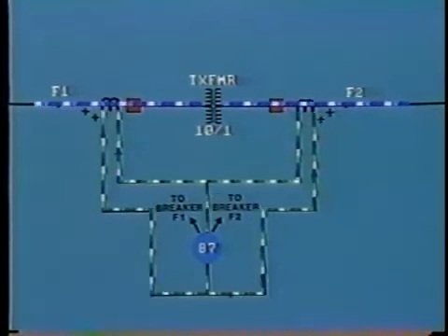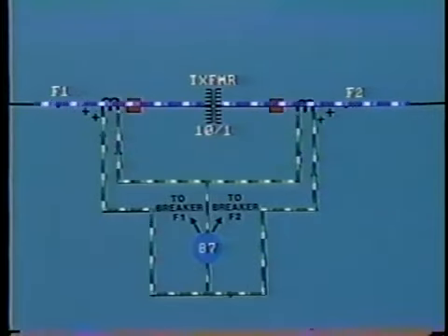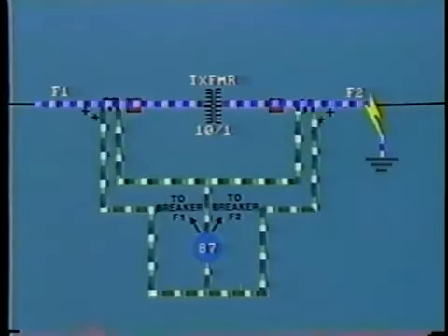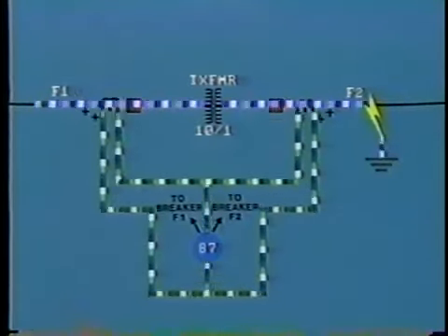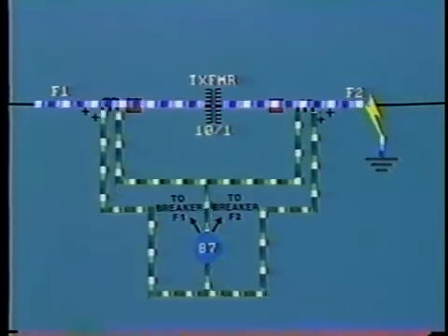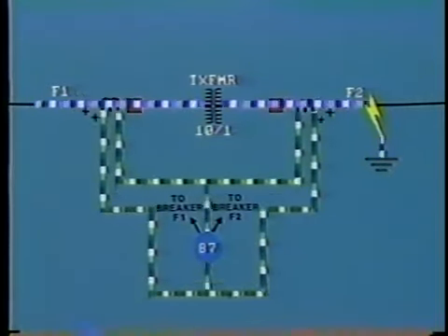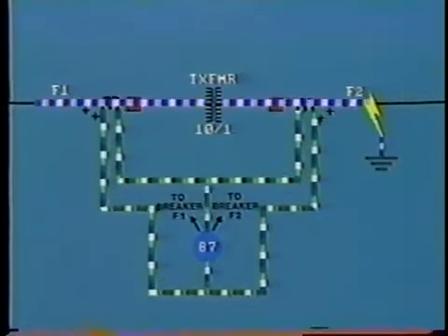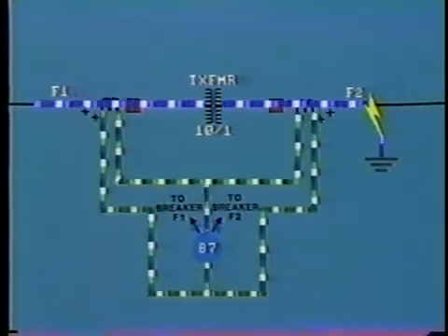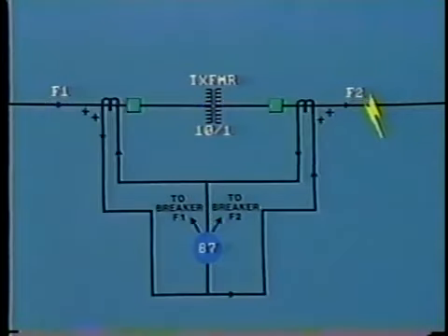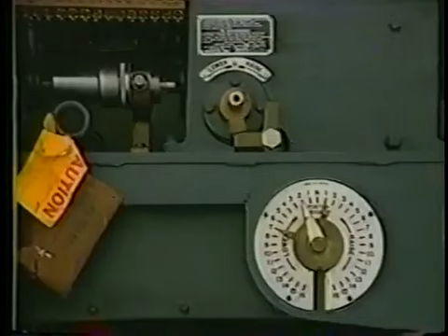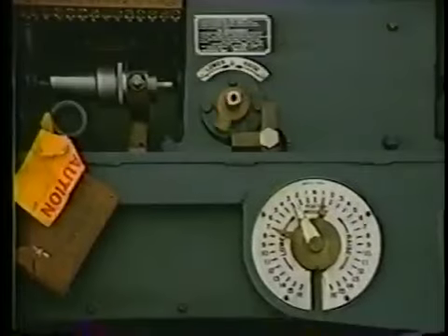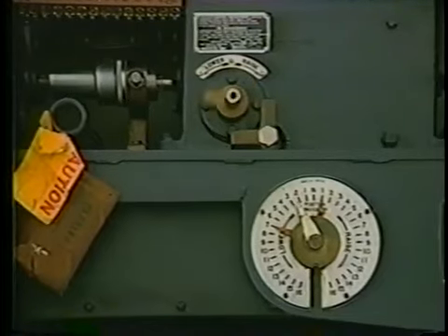close the tripping contacts. However, things may not be so comfortable where we have an external fault which causes a high current to flow through the transformer. In this case, the CTs will be measuring a balanced condition, but the error will be magnified and may cause the relay to operate. Similarly, transformer tap changers introduce problems with CT ratios.